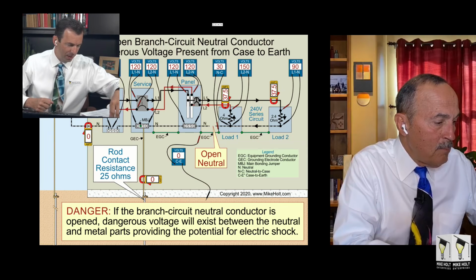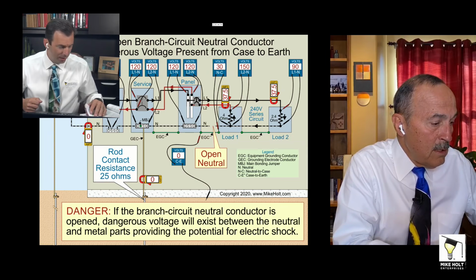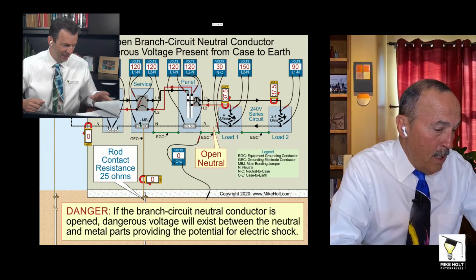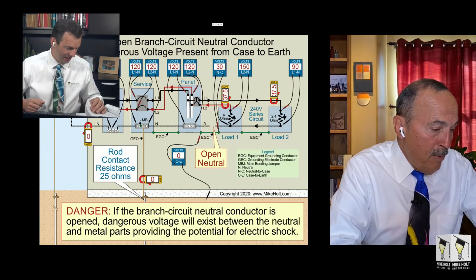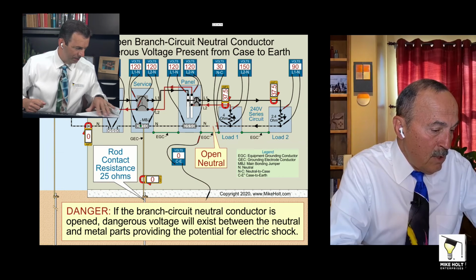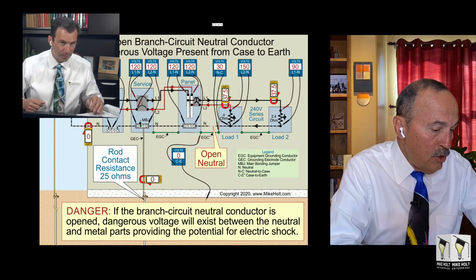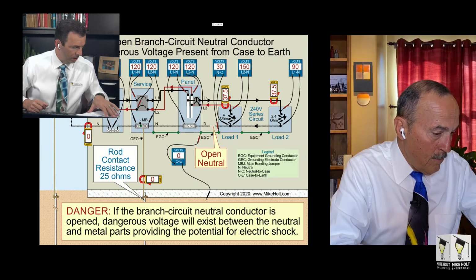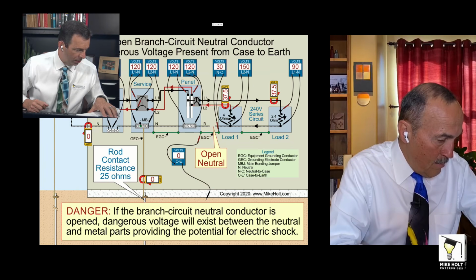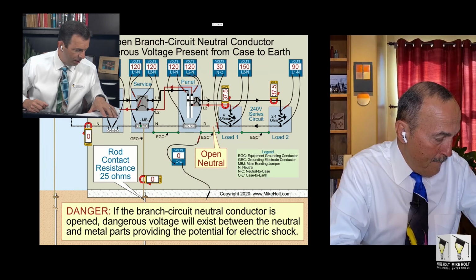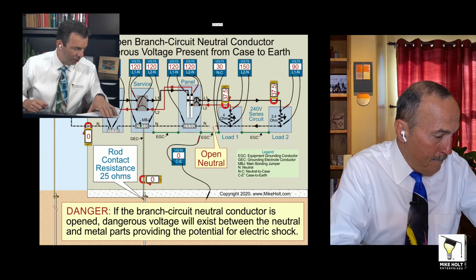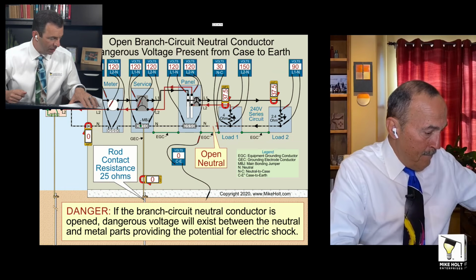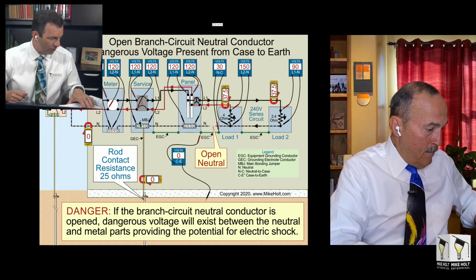Hold on, Brian. Let's wait till at least I get to it. I know it's highlighted. Let me read it. A means shall be provided in each metal box for the connection of an equipment grounding conductor. The means shall be permitted to be tapped. Okay, what am I missing here? What is research saying? 314.30(D): metal covers and other exposed conductive surfaces shall be bonded in accordance with 250.92 if the conductors in the handhole are service conductors.